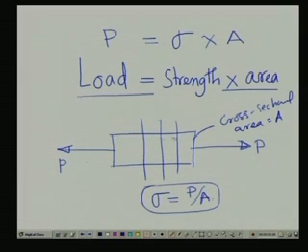If you go on increasing this load P, then at a certain time the material will fail. You can consider the failure to be yield failure. At the yield strength of the material it fails. By yield failure I mean that once the machine member enters the yielding zone, it goes to a permanent deformation, or a plastic state. So that also we can consider to be a failure.